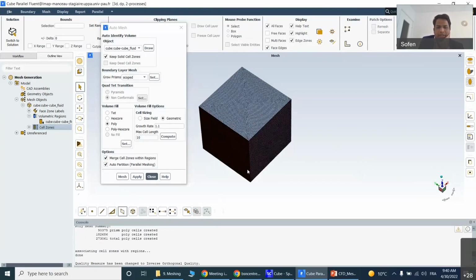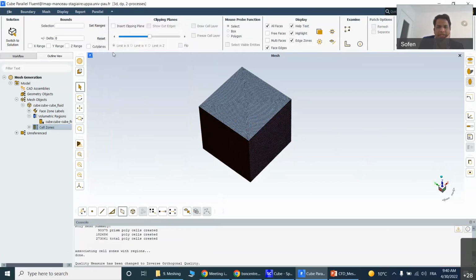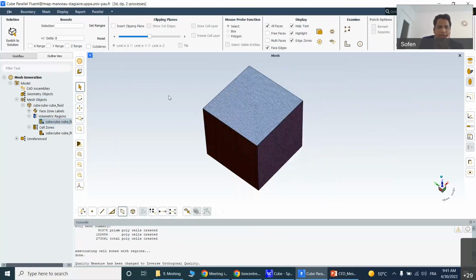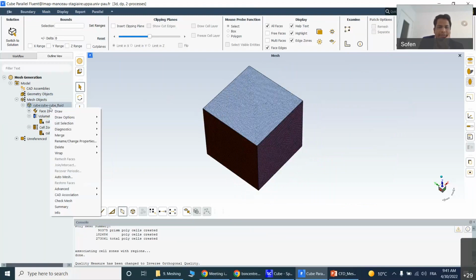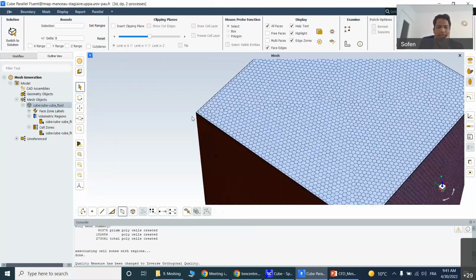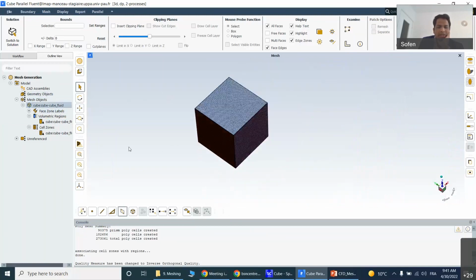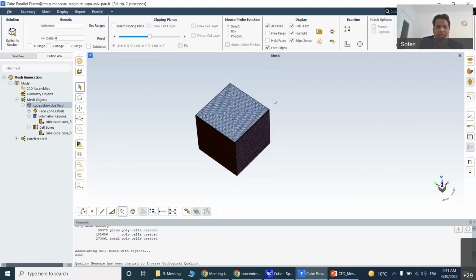Yeah. The volume mesh is generated right now. How to see it? Reset. Let's go over here. Draw all the boundaries. What we have seen earlier, you can see the reset. Notice the changes. Now all the triangular elements are combined together to form the poly element. Okay, draw. Now the poly element is done. We cannot see the triangular element because it's now converted to poly.